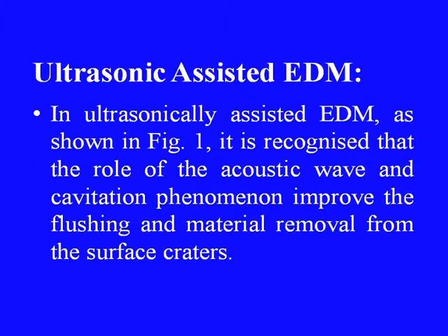In this process, as we can see in the figure later, it is recognized that the role of acoustic wave and cavitation phenomena improve the flushing and material removal from the surface craters. These process conditions are significant for micro drilling and production of slots and grooves.